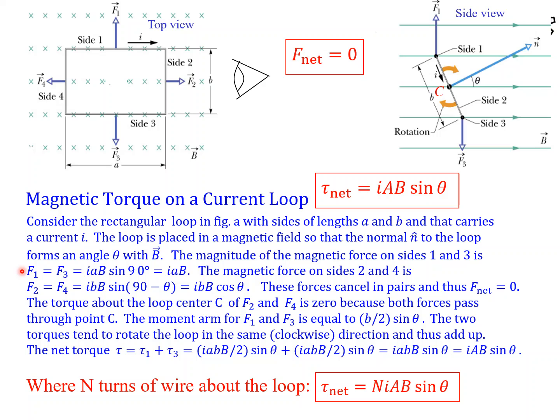And as we said, we've got to consider moments or torque. The moment of each of them about that point of rotation is the length here, b/2, times sine of that angle, sine theta. And for intuition on that, as we say, when theta goes to 0, they pass through the axis, so there's no torque. So that is as you'd expect. Got to add them both together to get the resultant torque around the axis of rotation.